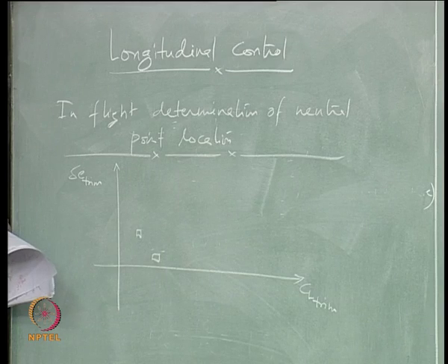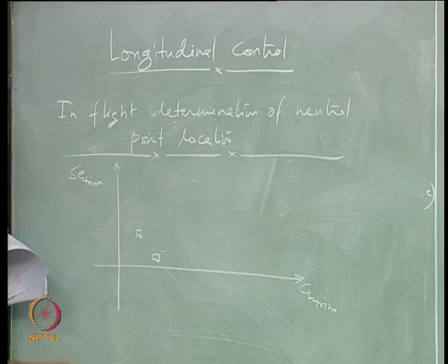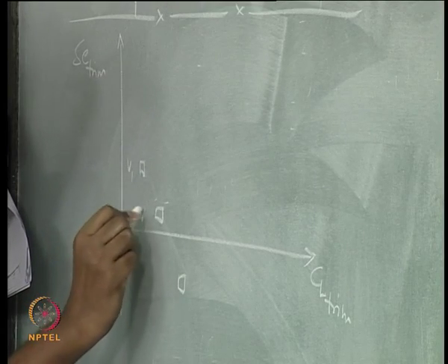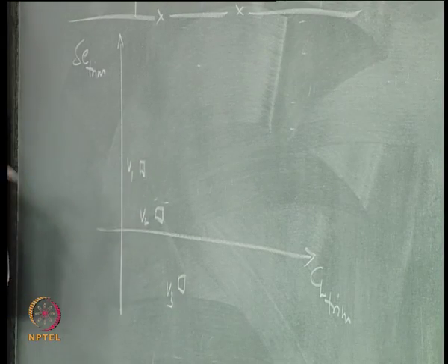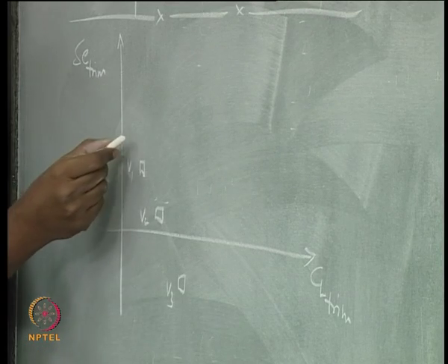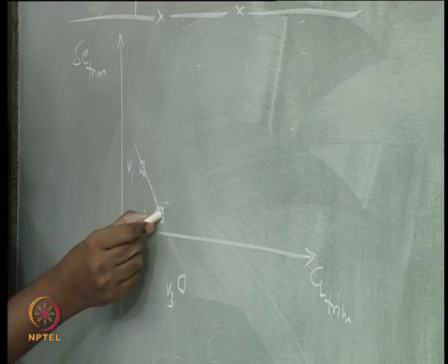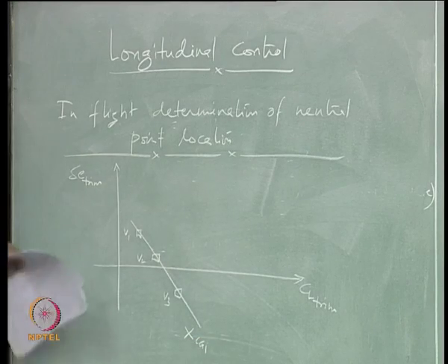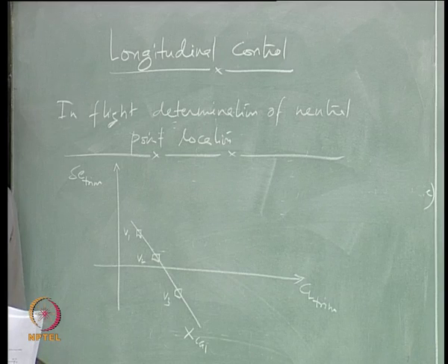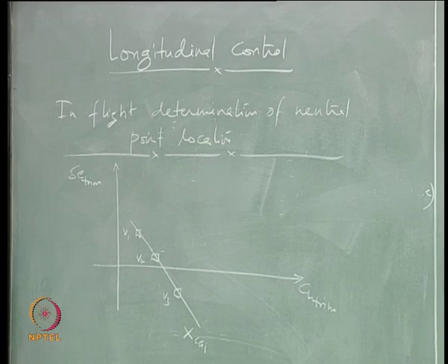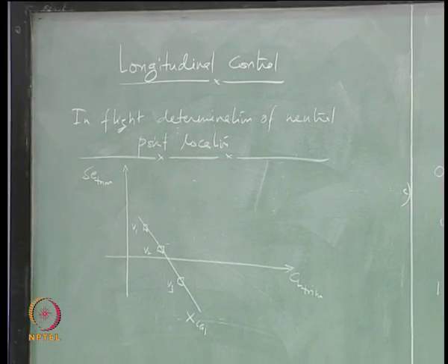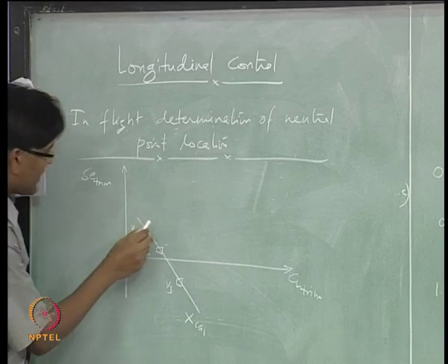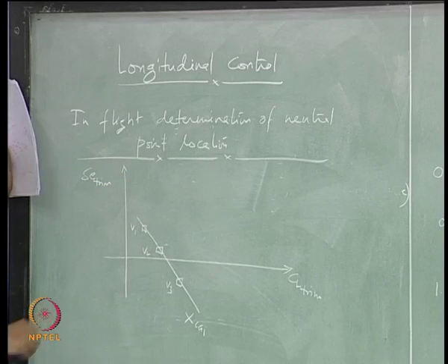Another point, right, one more change in speed, V1, V2, all trim values. Okay. And for one CG location you can actually find such a curve, right. Change something on the aircraft which will change the CG, and then again fly 3 different velocities, speeds.